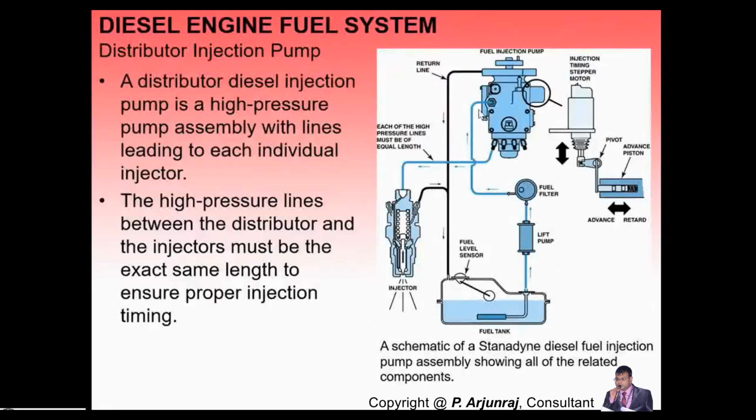Then it goes to the fuel injection pump system, and when the pressure is going to be higher, excess fuel is going to come in this direction; it's a return line basically. With the help of the fuel injection pump, the fuel goes to the injector, and it will inject. And again, it is basically spring operated. You even have a solenoid operated fuel injection pump also.